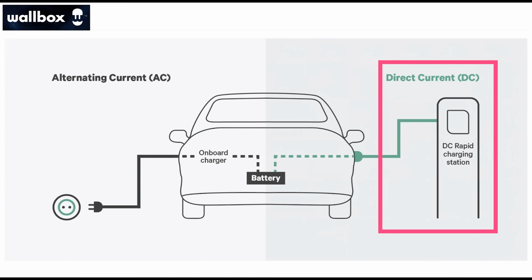But okay, the first thing we should appreciate is that there are two major sources of constraint. So one is how powerful the power electronics connected to the car is. If you drive up to a supercharger or a non-Tesla kind of charger that is 50 to 100 to 150 to 200 kilowatts, there's going to be ultimately a power limitation in the electronics in that charger. It can only deliver a maximum power of some number.